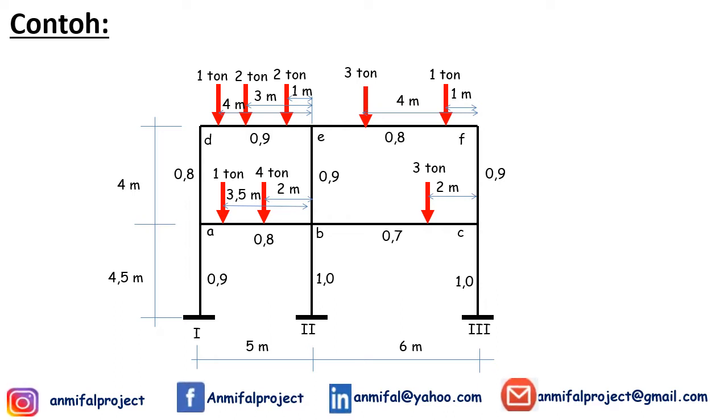Okay. This is really different between this problem or these examples and the previous examples in another video tutorial of Takabeya methods, because in this problem you should evaluate or calculate the bending moment at every node available in this frame structure system because of the unsymmetrical reactions.